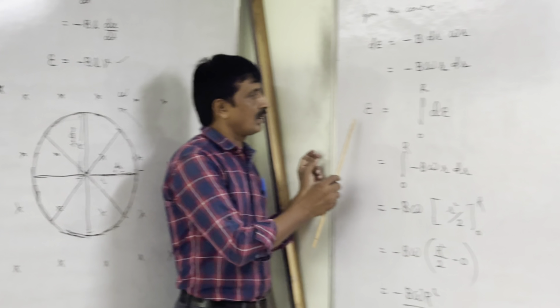Here we are moving this wire in this direction with velocity v. So EMF is generated in the coil, in the loop. But in which direction is the current moving? Whether it is anti-clockwise or clockwise. It must be anti-clockwise, because we know that the magnetic force acting on a current element kept in a magnetic field is given by dF equal to I dL cross B. But here the magnetic field is uniform, so we can consider I L cross B. IL is this, B is this.